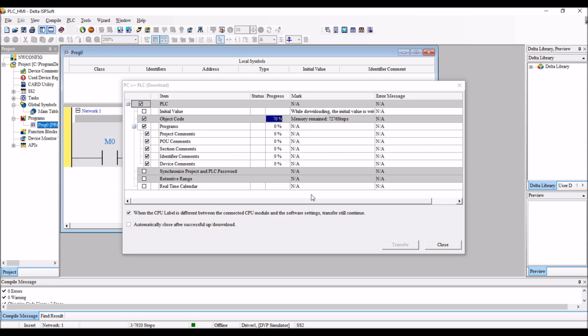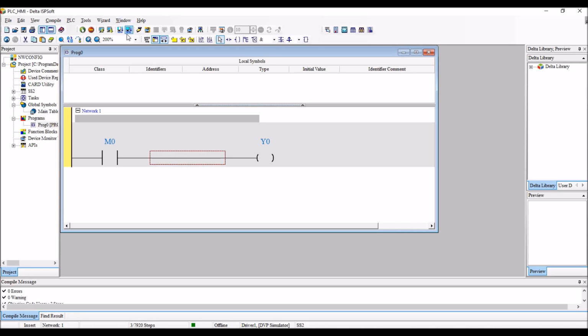In your case it is real hardware, a real PLC, when you are practicing in the lab, so you have to download to the real PLC. Then go to online mode and make sure it shows Run. If it is in Stop mode, it is not going to show output, so go to Run mode.